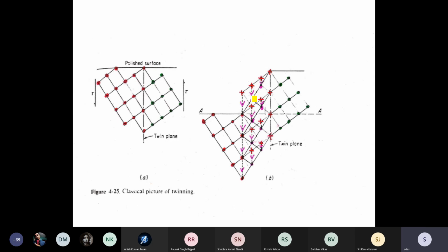And every single atom in the twin region moves by a fraction of a distance along a plane towards a particular crystallographic direction. The magnitude of the movement, how much they move, is a function of how far the atoms are lying from the twin plane. So it's just like a military formation in the march past. Everybody is moving by the same distance. So in dislocation, you see atomic movement only in the vicinity of the localized lattice disturbance, that's the dislocation line.